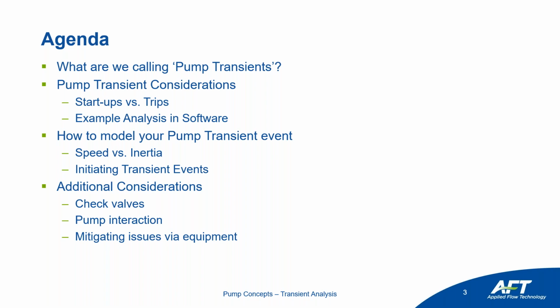And in these cases, we won't go into too much depth on each of these considerations, but there are other resources that we can reference. So how do you address things like check valve slam if you have a pump that's tripping and your check valve is going to prevent that reverse flow? That's something that could be in the realm of pump transient analysis, but we won't go into too much depth here. In fact, I've actually done a webinar this year focused solely on this transient check valve analysis. Look, the same thing with pump interaction.